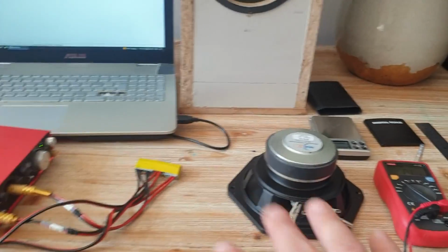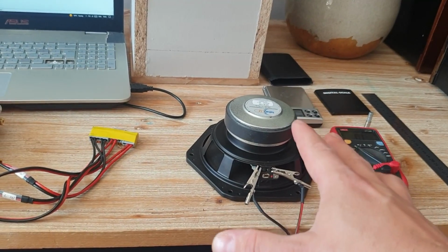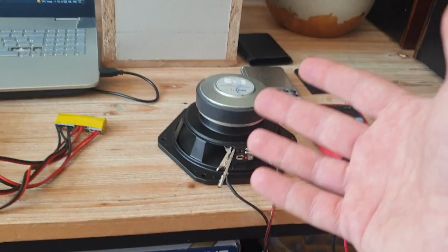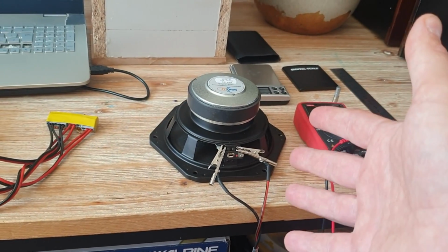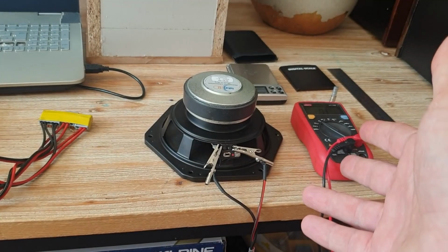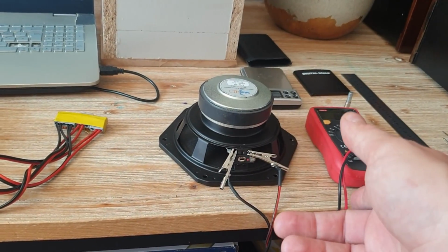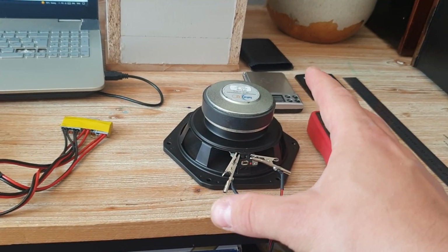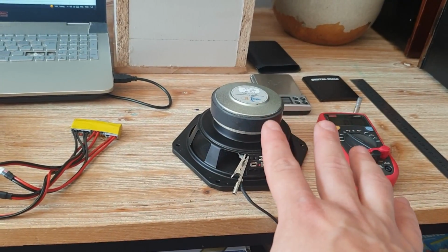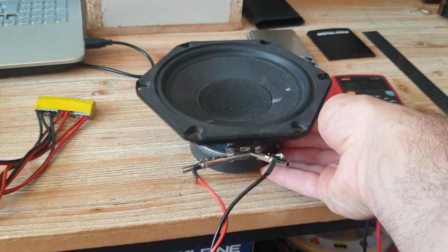Now, all the TS parameters of the driver are derived from the impedance plot, because the impedance plot shows you how the driver reacts to any kind of frequency, and TS parameters are just mathematical equations that you can manipulate and calculate one from the other. And what we need is to have two impedance graphs. One is in free air, which is like if you just have a driver like that. I'm going to turn it upside down, just like that.